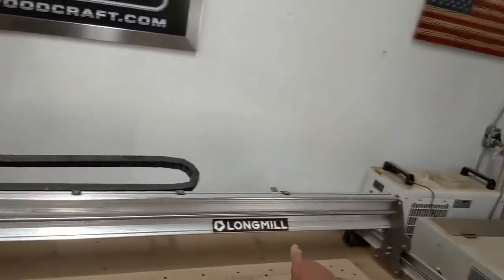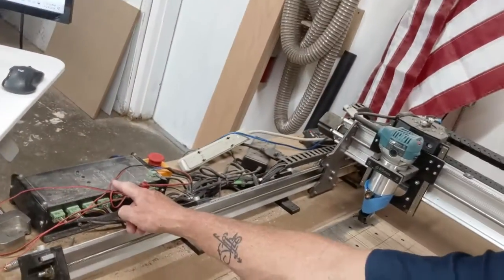Basically, all CNC routers have a brain, such as the Long Mill MK2 has this black box here. That's the brain of the machine. And in there are requirements, so the machine knows how to run. And those requirements are the G-code itself. The post-processor tells the G-code writer of the software to insert certain commands at certain places so that the machine knows exactly what to do and where to go during different processes.